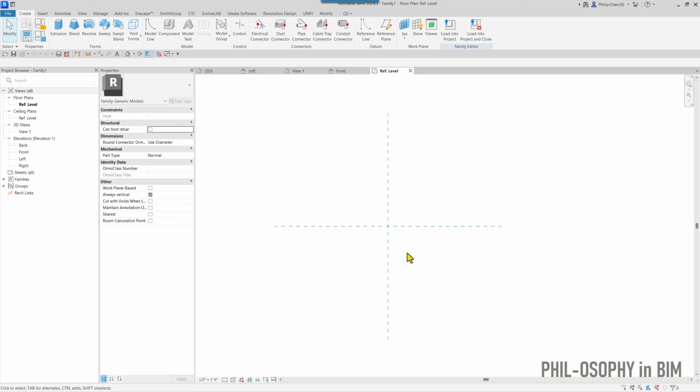Let's talk about the first technique, which is the old school technique that's been around for years. It is called reference line. First and foremost, in Revit families you have two different things called reference line and reference plane. For this demo, we're going to be using reference line for the most part. They have different purposes in a Revit family, so don't mix them up and use them however you feel like. They serve different purposes and different goals.